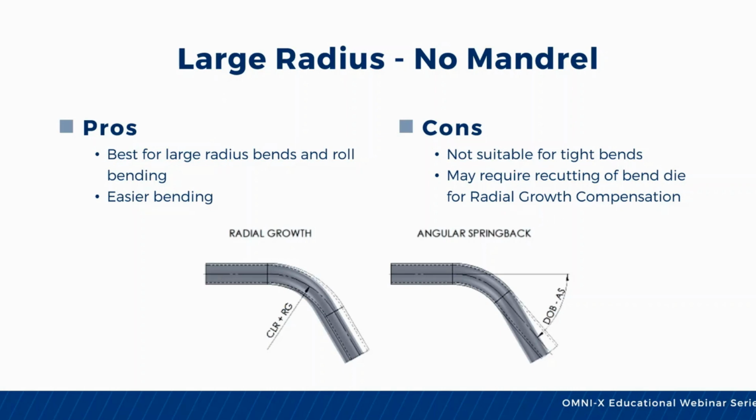At around 4D of bend, for example, a 2-inch OD on an 8-inch CLR, in order to avoid a mandrel, you would need about a 15 wall factor, which would be about a 1/8 inch, or 0.125 inch, 125 thou wall. For 5D of bend, or 10-inch CLR on the same 2-inch OD, you can avoid a mandrel with a 25 wall factor, which would actually allow for an 80 thousandths wall on a 2-inch OD too. The selection chart that Jack reviewed earlier should be able to show you how to avoid a mandrel with no